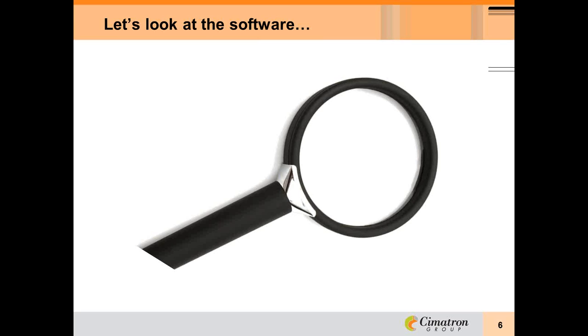Good. Okay. The question is, as the die set increases or decreases, does the software go ahead and change the pin and bushing diameters? Yeah, again, it's totally customizable to wherever you want. I've seen customers who have 3 different die sets: small, medium, large, where those pin sizes are set, and other people who just keep it as one die set and have it tied to a formula. So if the plates get beyond a certain size, it will automatically jump up to the next bushing and leader pin size.